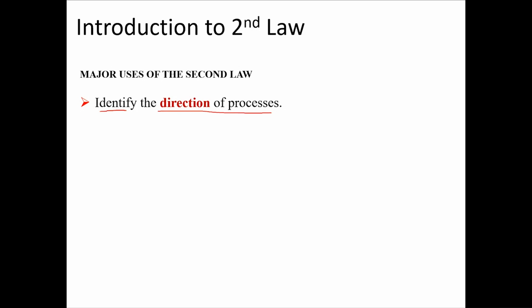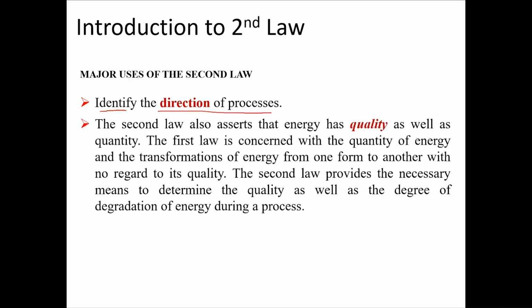This is the first thing, but this is not the only thing extracted out of the second law. The second thing is that it gives you information about the quality of energy. The first law essentially deals with the quantity. The first law is concerned with the quantity of energy and the transformation of energy from one form to another, with no regard to the quality. However, the second law provides necessary means to determine the quality as well as the degree of degradation of energy during a process.